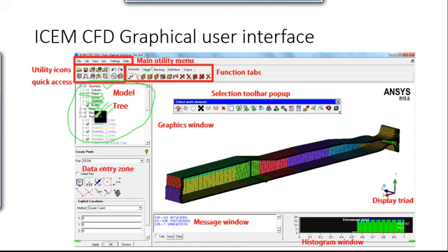And then there comes the parts. The parts are basically the derived or the subsets of the geometry. So parts can contain the point, curve, or surfaces, or the combination of the point, surface, and curves in one single part. For single surface, for the two surfaces, you can have one part or you can have two different parts. Also, the parts hold the meshing information when you define the body or the material point. So this will be shown in the part list. So that is related to the mesh, which holds all the mesh inside this geometric model.